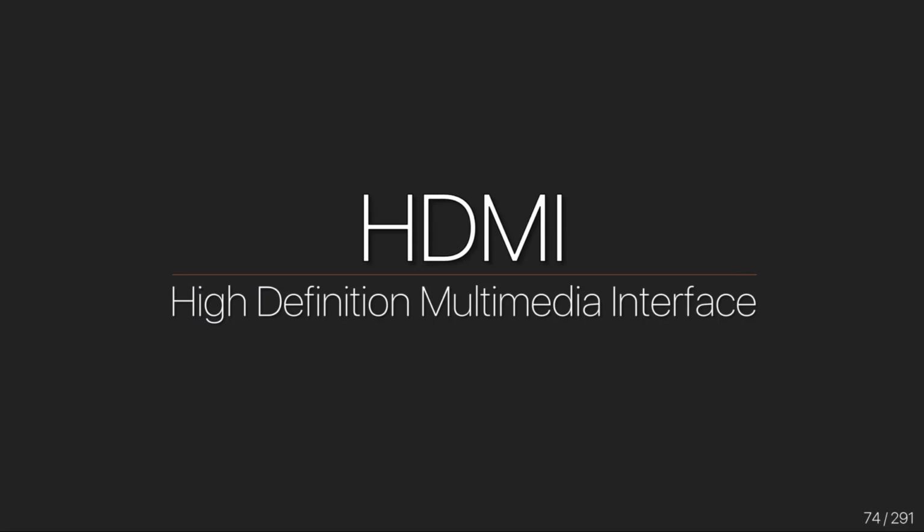There are analog EDIDs. So if you have a VGA output, you can find that some VGA cables are missing the pins for the DDC channel, and if you plug that device in, let's say you're plugging a display into your laptop, you might see that display as a generic PnP monitor. That's normally an indicator that the DDC pins aren't there, or there's no EDID being read. So you can send a VGA signal without an EDID, so you don't need it.